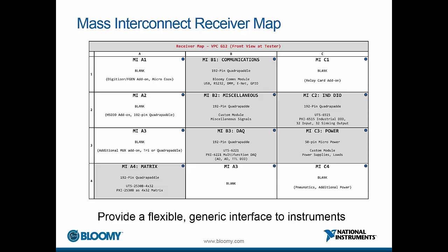Because every module corresponds to a particular set of instrumentation, the pinout of each module must be identified. In some cases where an off-the-shelf PCB interface is available, this pinout is fixed based on the instrument and cabling connections. In other cases where the module is more customized, you have a bit more freedom when laying out your pinouts. Let's take a look at one example of a module pinout, the power block.